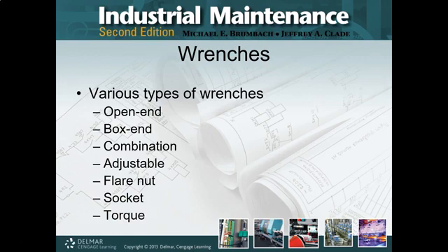reduce that, we created the box end. And in this case, the wrench completely encircles the nut or bolt and increases the points of contact, whereas the open end wrench typically only has really two points of contact on the nut or bolt. It kind of sucks because that is like the fastest way to strip out a nut or a bolt. The box end, because it encloses more of the bolt or nut, we now have more points of contact. And so we reduce the risk. I didn't say it was impossible. We reduce the risk of stripping out that nut or bolt.